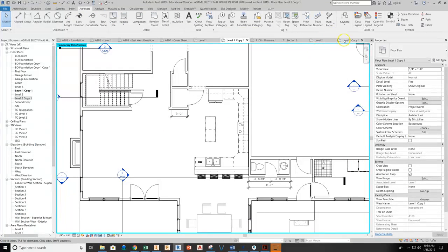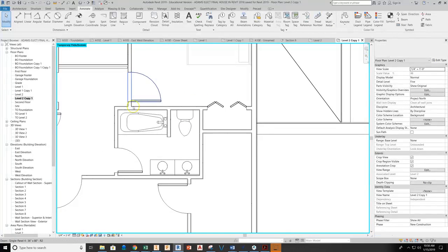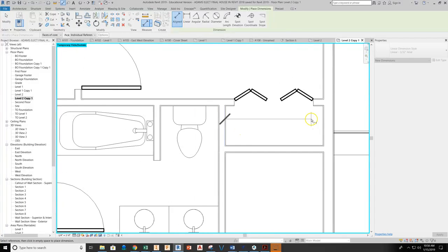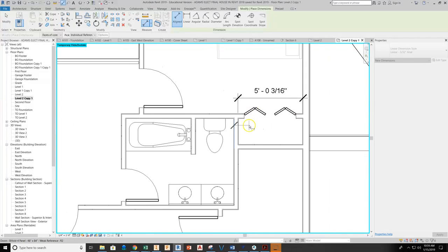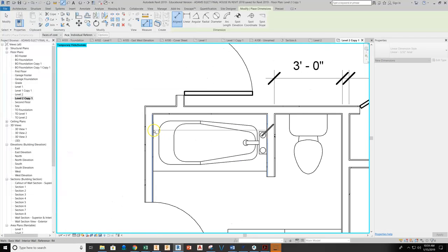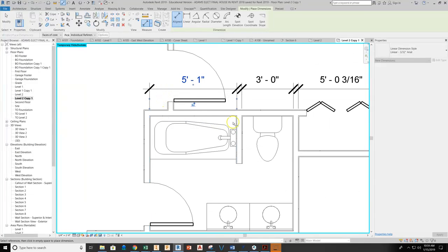Now if I jump up to the second floor, this is an area where, with closets and bathrooms on the inside of the house, is a very good place you can show some internal dimensioning, where I pull from stud face to what would become the inside stud face of the room here to give this closet wall position, and then also position for the area for the commode. And then also we'll go ahead and locate the interior wall here to the stud face for where the tub's going to get located.